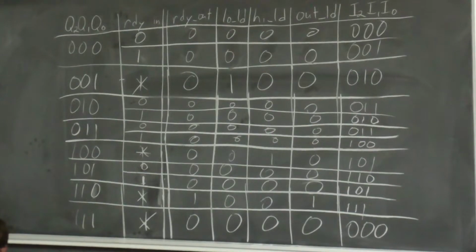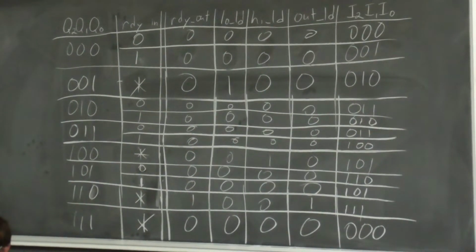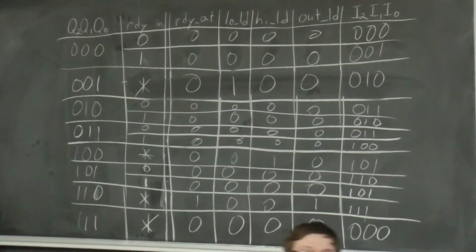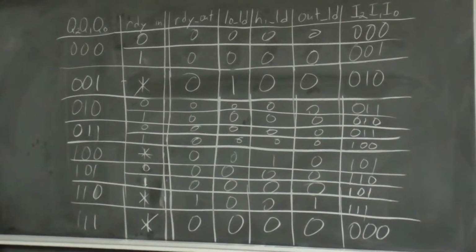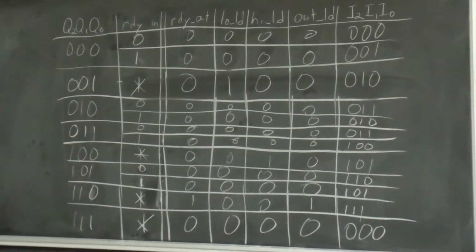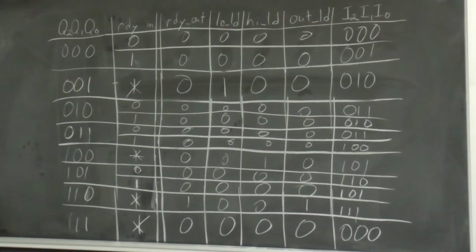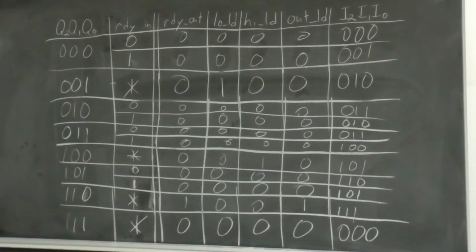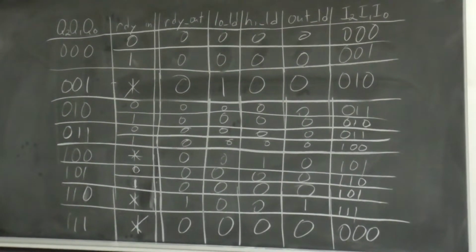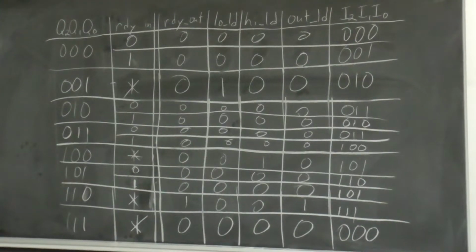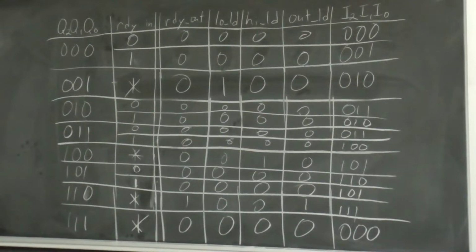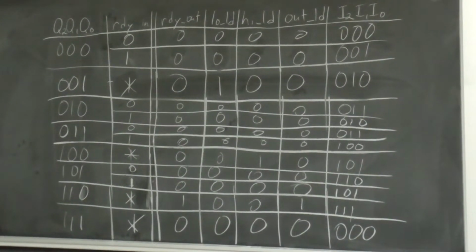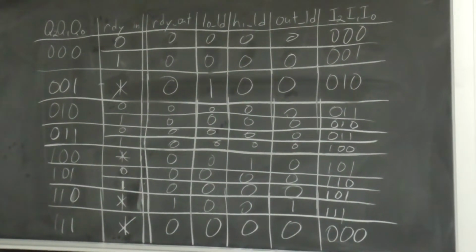Any questions? I mean, that's logic, so. Question? What would you use that table for? Is it just a different way to show that information rather than that diagram? Or are you going to make a Karnaugh map out of it? You would make a Karnaugh map out of it, derive minimized state equations, and from those minimized state equations you can derive combinational logic circuits. In fact, why don't we try that?